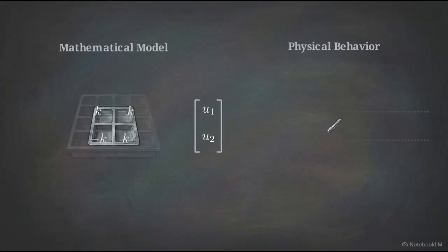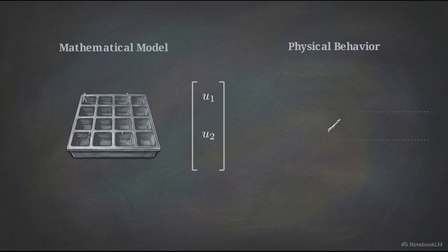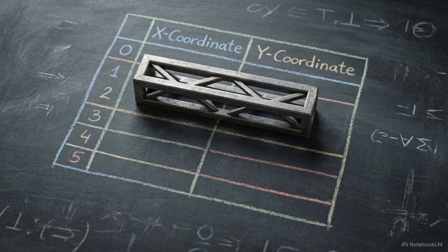To bridge this gap, we first expand the architecture of the equation so that it recognizes two-dimensional space. We introduce redundant degrees of freedom, sliding the existing rows and columns apart to create a 4x4 matrix. We fill the new slots in the stiffness matrix with zeros and add the lateral displacements, v1 and v2, to the displacement vector. These additions function as zero-energy equations. This change in formatting does not alter the physical behavior of the bar. While the physics remain one-dimensional, the matrix is now wide enough to accept two-dimensional data.